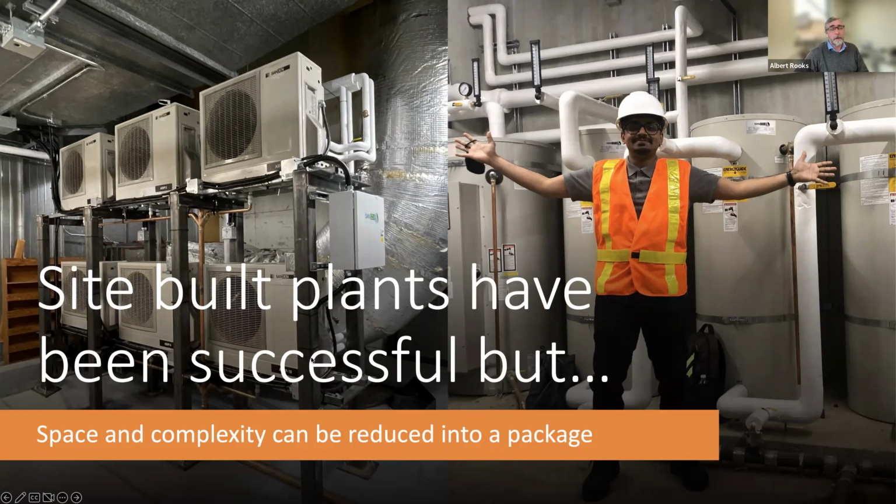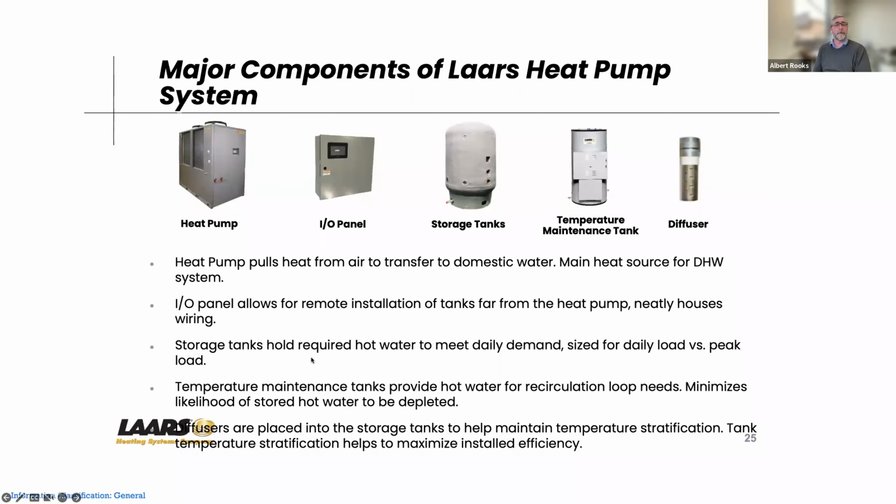On the right-hand side is a new build in downtown Vancouver. Those are 419-gallon tanks, so we got 400 gallons of storage, and a bunch of heat pumps paired to it. But it really fills a mechanical room, takes quite a bit of space, takes a long time to build. Somehow we have to teach designers to design, and then teach installers to install, because it's not the simplest system, because the controls are really quite important.